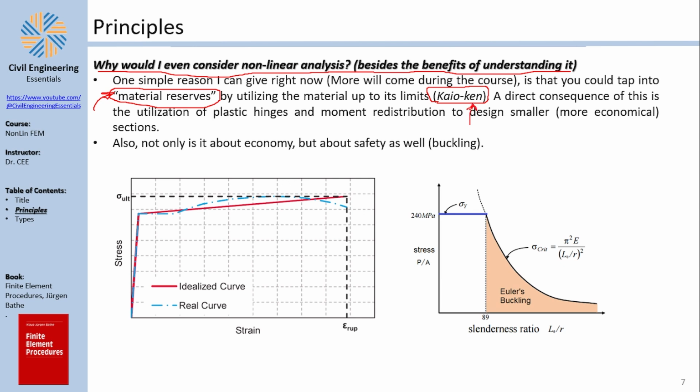Again, that's something that my teaching assistant told me to say, because it seems that you are accessing or tapping into reserves. But of course, since you are tapping into reserves, the reserves are no longer available for you, and this means that you need to be very careful when you design. You can get away with some approximations you do in the linear domain, because when you analyze linearly, you always have this get out of jail free card by saying that, you see, I'm doing linear analysis, although the reality is nonlinear, so we have reserves.